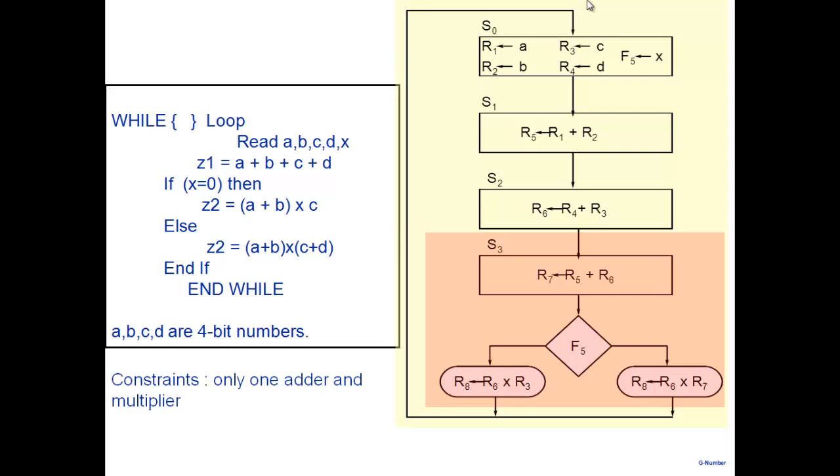All right. So a more general picture of an ASM chart is, well, you may have these simple state boxes where you have unconditional statements. You're not testing any condition and you're simply doing the transfer. But more generally, this is what may happen here. You may have some unconditional register transfer statements, and there may be some conditional register transfer statements.